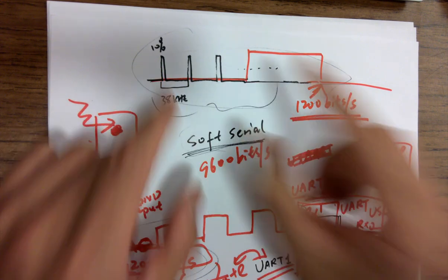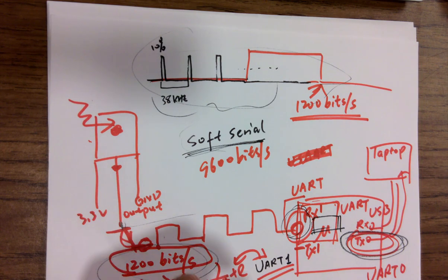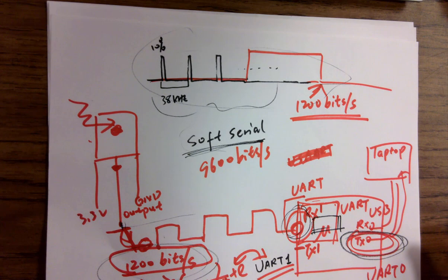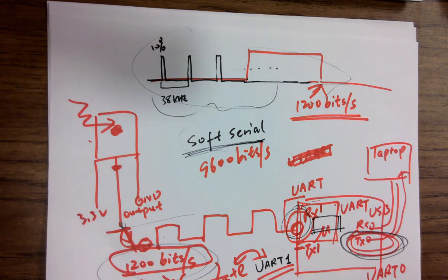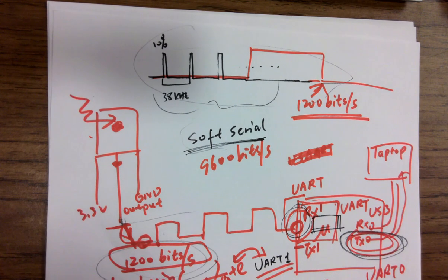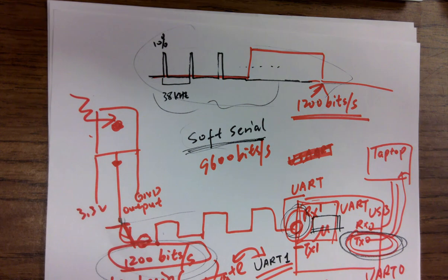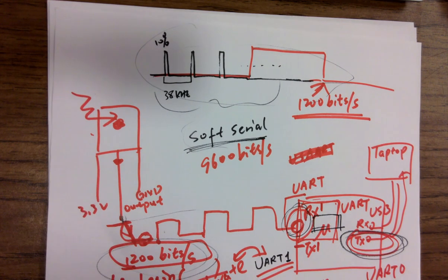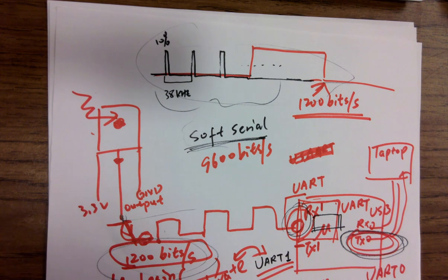So I turn on. Remember the module I showed you, the 3 lines? That one turns on the PWM. I do that first. Then I turn on the timer. Remember how to turn on the timer? Through the CS bits, the prescaler, so it's getting turned on, and then directly assign a value to TCNT3, so the value is stored in there.